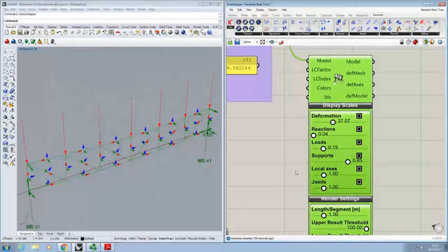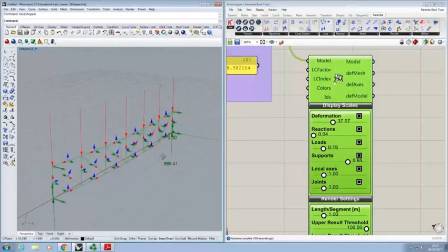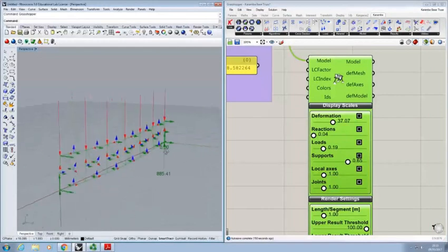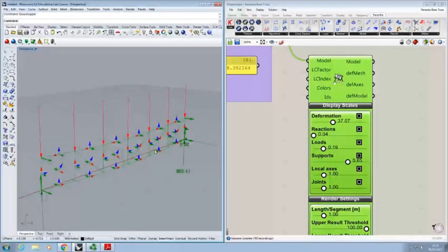The local axis is quite important when you have elements which are not linear, or when you want to align beams with shells, for example in a stiffened shell model where you have a 2D element model with beams running along the edges of shells to stiffen them up.